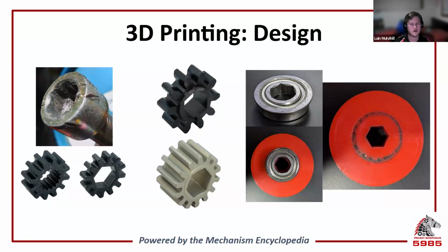Another thing you'll need to remember is shrinkage, because 3D printed parts are produced by using melted plastic. As the plastic cools down, it shrinks, meaning that your holes become smaller. To fix this, I generally add 0.3mm to my dimensions to combat the shrinkage.